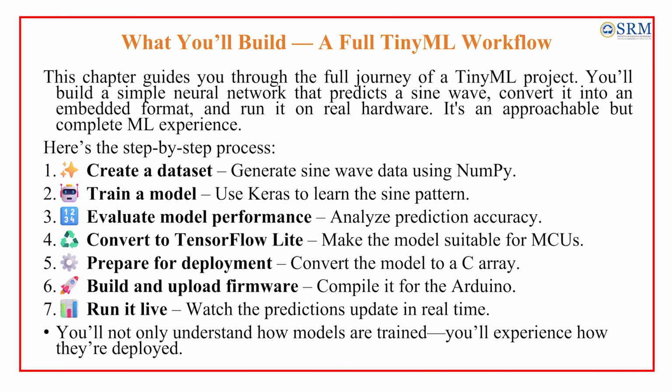This slide outlines the full TinyML workflow. Here we are going to guide you through the full journey of a TinyML project. You will build a simple neural network that predicts a sine wave, convert it into embedded format, and run it on real hardware. It's a simple, approachable, complete ML experience. First, we are going to create a dataset, in this case a sine wave, using NumPy in Python.